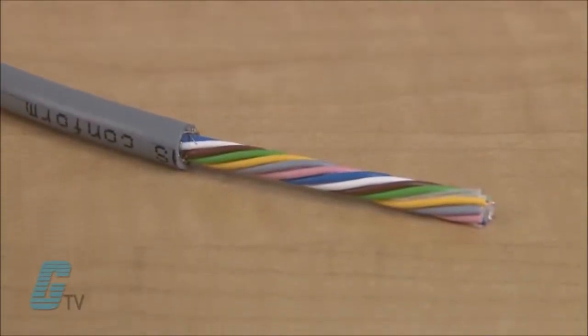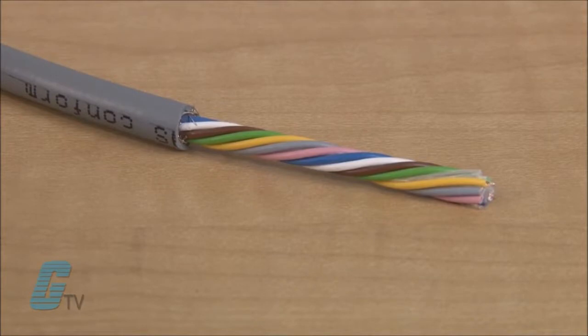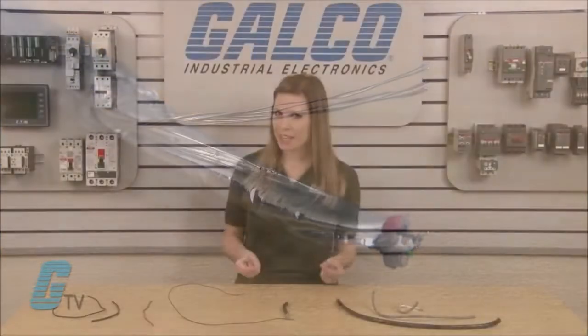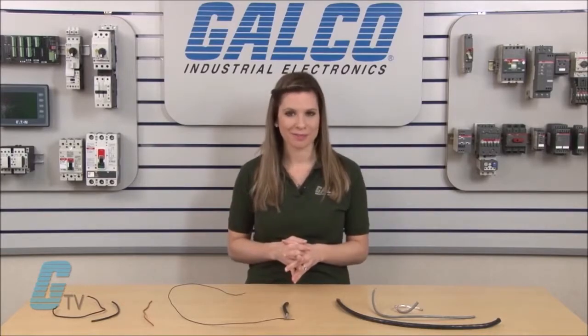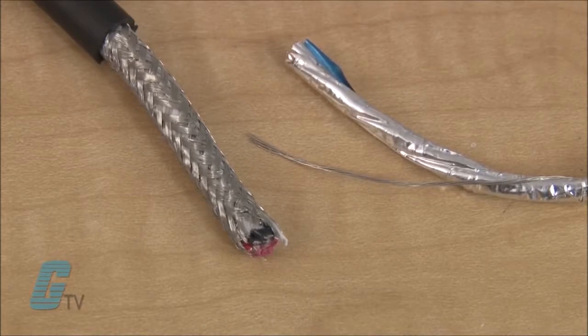Some cables may serve as a conduit with other wires inside that in turn are comprised of groups of stranded wires. Cables also may have a shield or armor surrounding the wires. This is an electrically conductive material designed to prevent EMI, electromagnetic interference, or radio frequency interference, as well as to provide an extra level of protection to the wires. Shields can be braided, spiral, or wrapped in a foil.